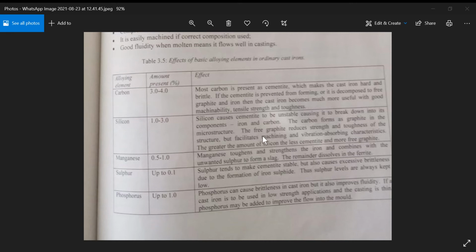And if you have a look, these flakes are essentially voids in the structure, which make the grey cast iron weak in tension, however strong in compression. Remember, tension is pulling apart, compression is pushing in. And to reinforce that point, pearlitic grey cast iron exhibits good toughness, good compressive or squashing strength.